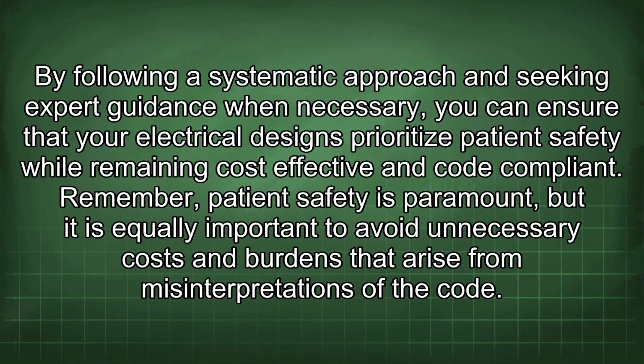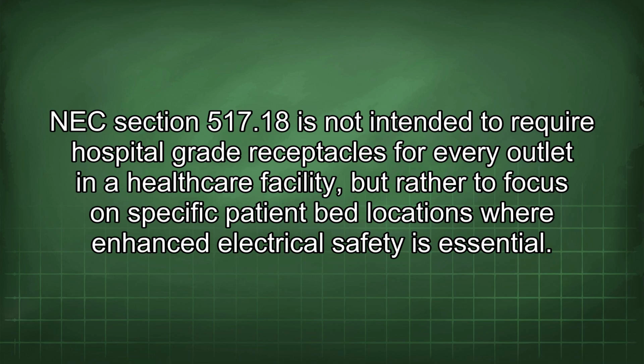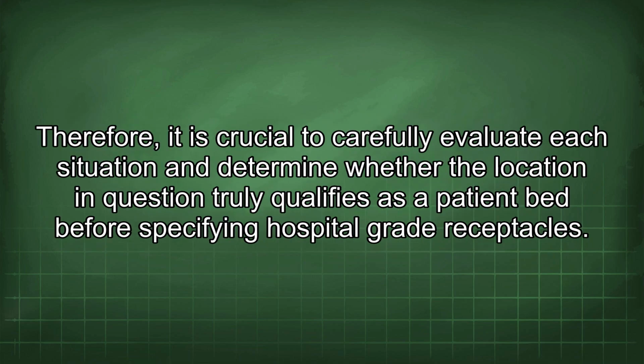Remember, patient safety is paramount, but it is equally important to avoid unnecessary costs and burdens that arise from misinterpretations of the code. NEC section 517.18 is not intended to require hospital-grade receptacles for every outlet in a healthcare facility, but rather to focus on specific patient bed locations where enhanced electrical safety is essential. Therefore, it is crucial to carefully evaluate each situation and determine whether the location in question truly qualifies as a patient bed before specifying hospital-grade receptacles.